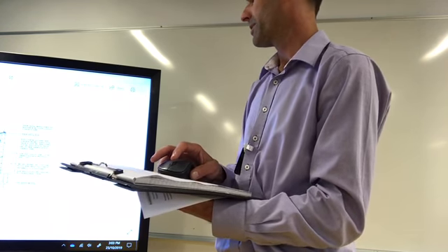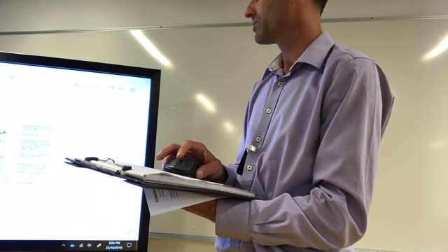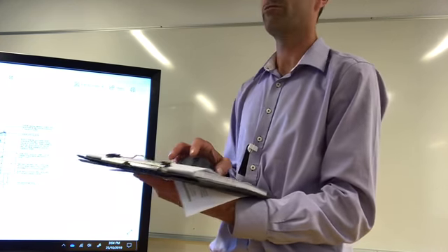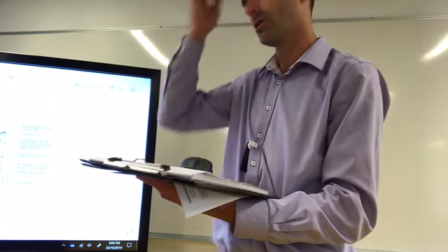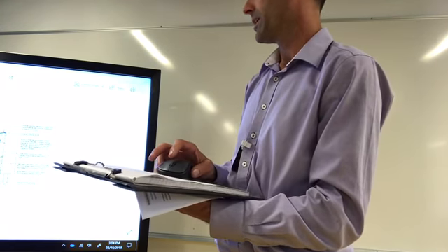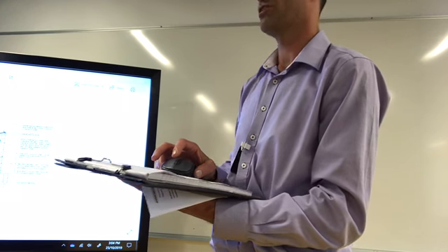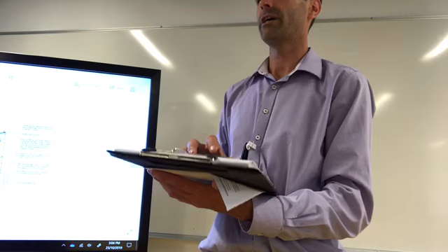But the thing that you should be aware of and should show is your parapet flashing here as well. The thing that you have to remember with any of your flashings is that flashings higher up lap over top of flashings that are lower down.